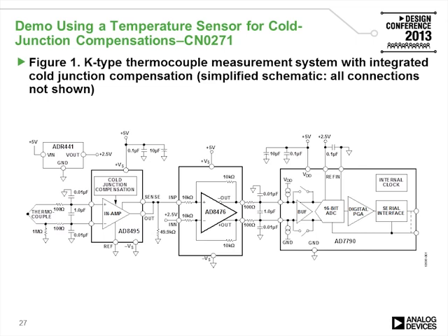You can build up a whole system, and our circuit note from the lab, CN0271, shows a complete circuit for capturing the signal from a thermocouple through a buffer amplifier and into a high-resolution A to D converter.